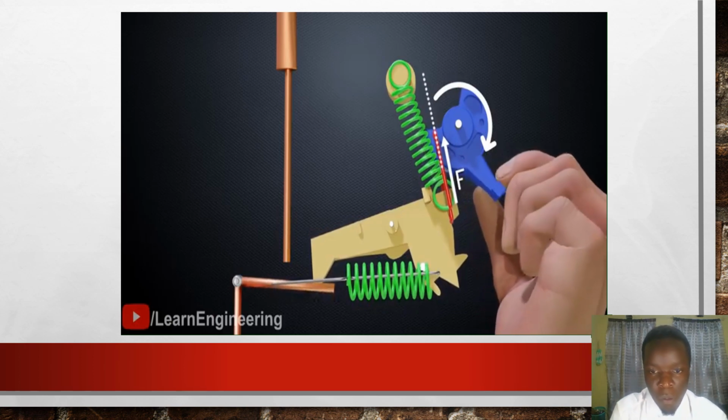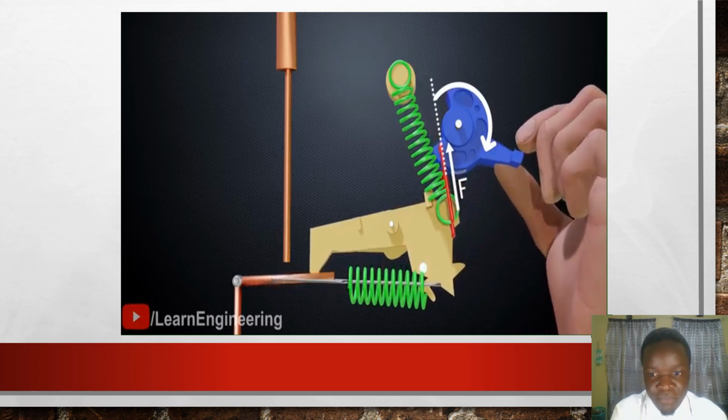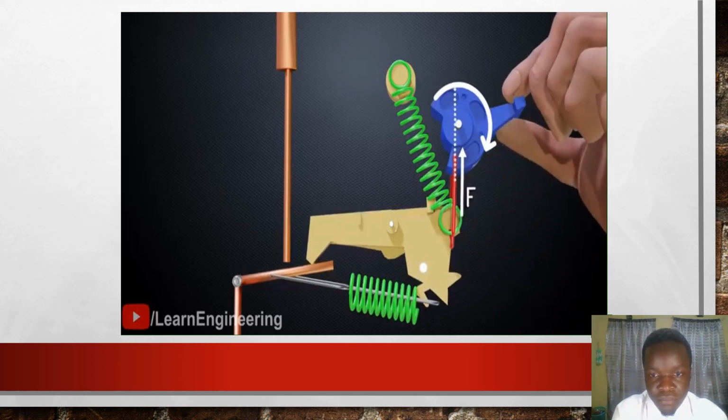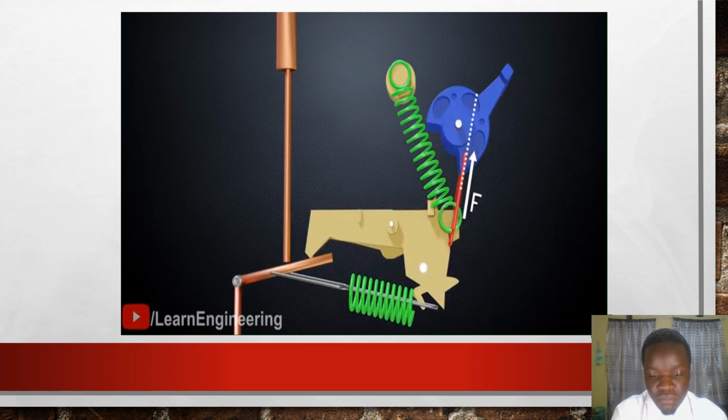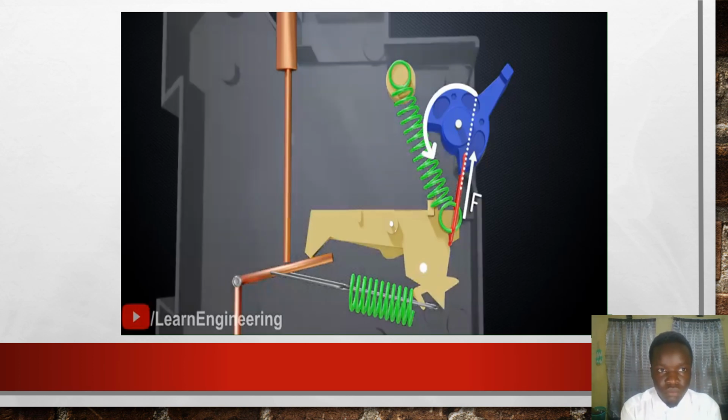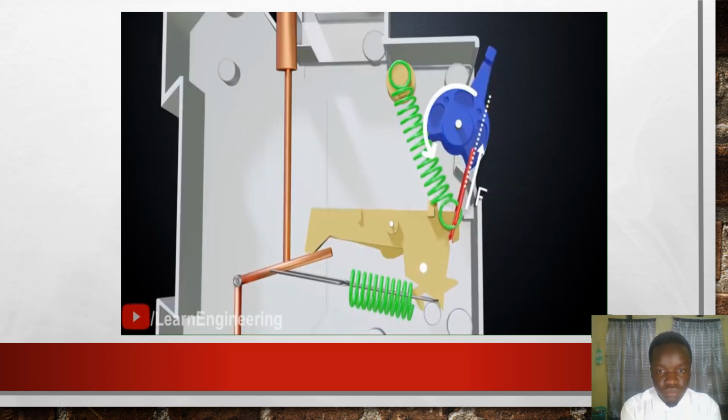However, if you push the lever farther up, do you notice anything peculiar about the offset distance? It suddenly becomes positive, which means that after a critical limit, the torque will act on it in a counterclockwise direction. When the MCB is on, this will be the position of the lever. The structure of the MCB will block the lever from rotating further counterclockwise.